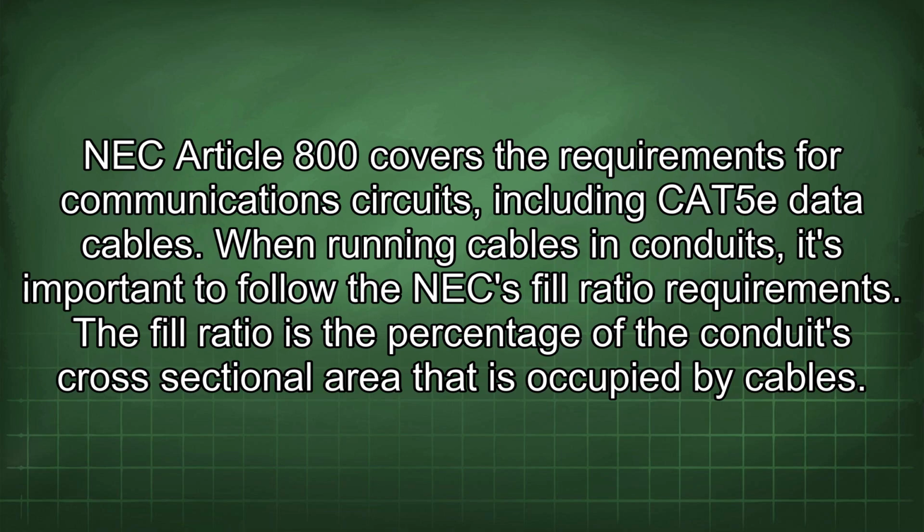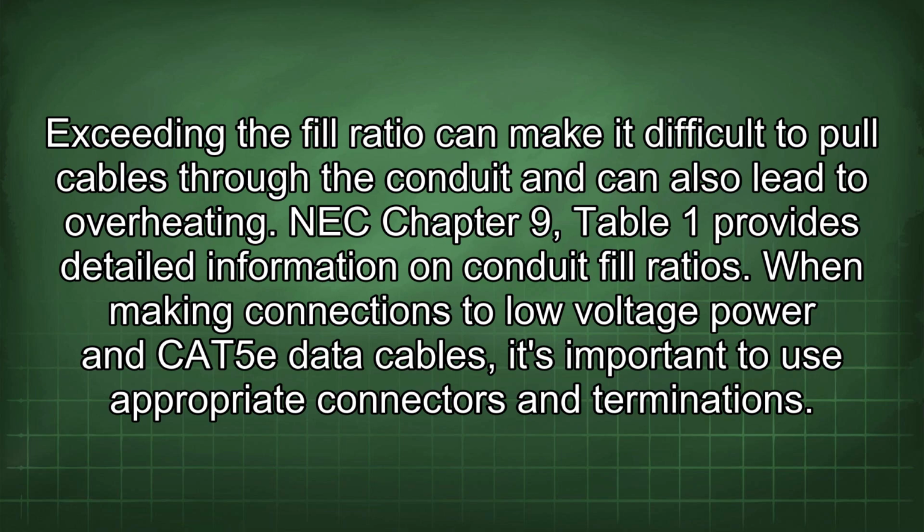When running cables and conduits, it's important to follow the NEC fill ratio requirements. The fill ratio is the percentage of the conduit's cross-sectional area that is occupied by cables. Exceeding the fill ratio can make it difficult to pull cables through the conduit and can also lead to overheating. NEC Chapter 9, Table 1 provides detailed information on conduit fill ratios. When making connections to low voltage power and CAT5e data cables, it's important to use appropriate connectors and terminations.